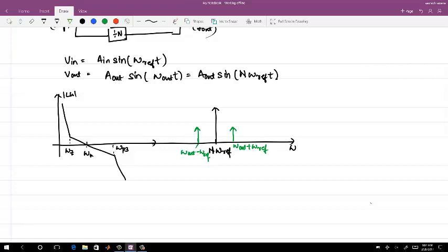The confusion was that the unity gain bandwidth of the PLL, which is omega u, is surely lesser than omega ref. Normally we try to have it less than omega ref by 10. Let's say your omega ref is occurring somewhere here, just for example. Unity gain bandwidth is this.